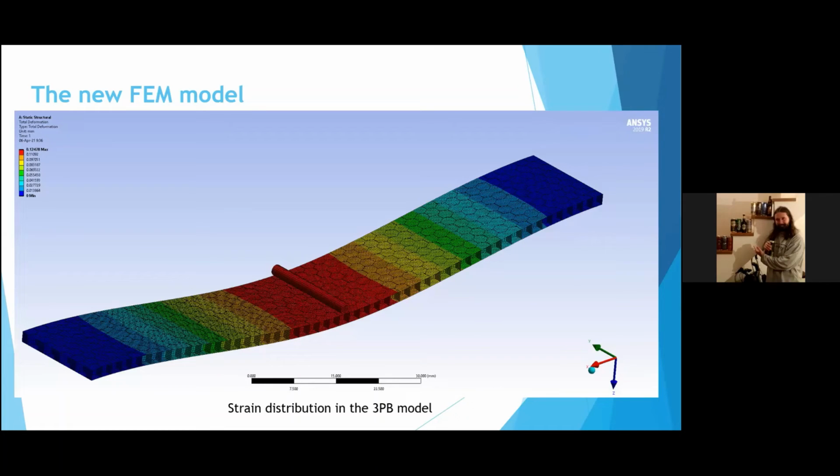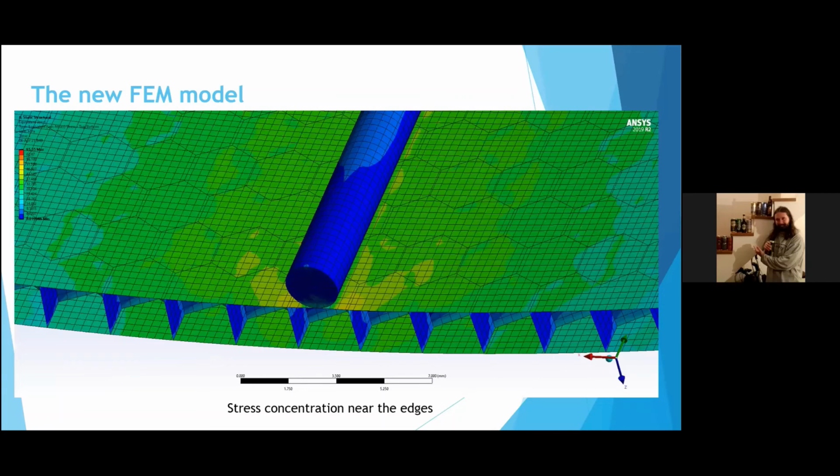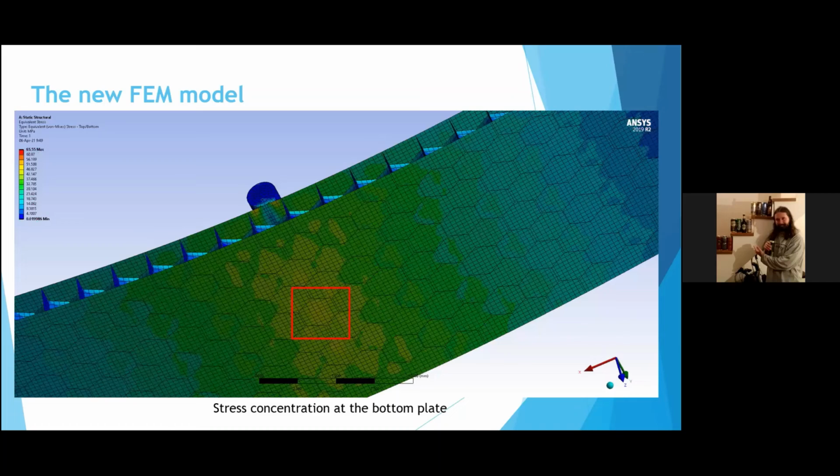This is the strain deformation, which was as expected. And here we have the stress distribution. The highest values were in some small parts of the support, so we can disregard that. The ones that are interesting are the ones closer to where the load was acting, which you can see here, very close to the load bar actually. And also on the bottom, with these having very similar magnitudes, so both will be considered at a later stage.